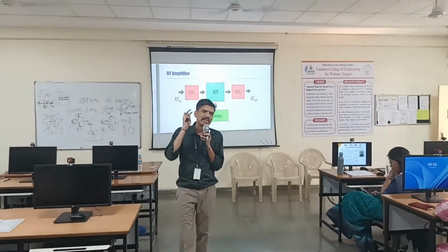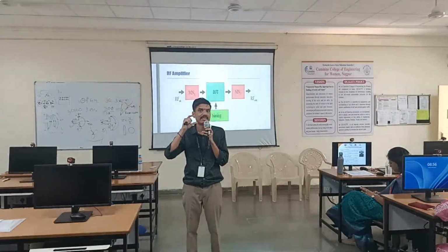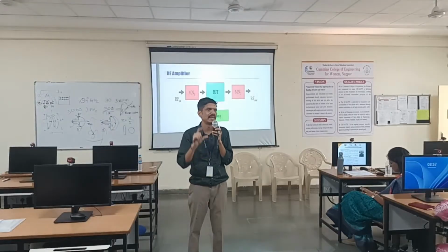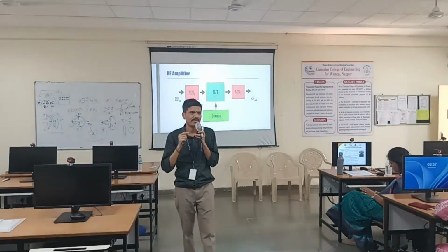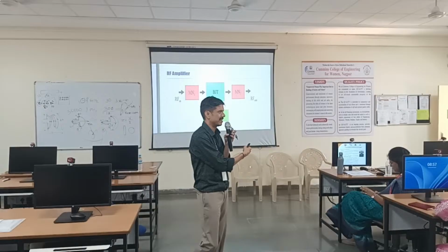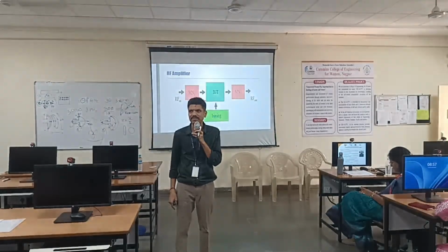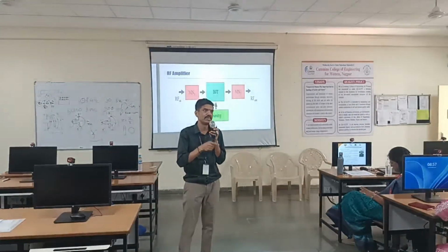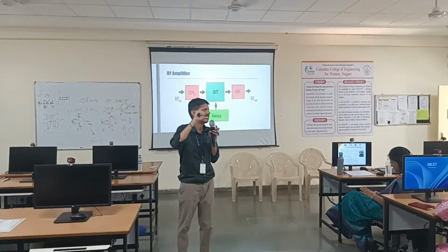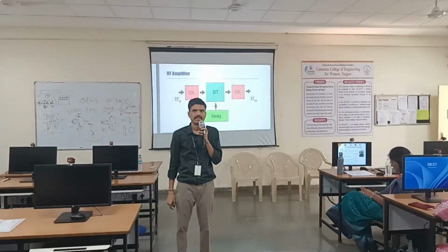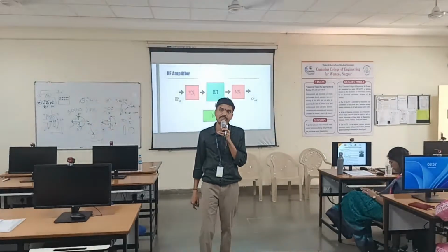See, there are 3 design parameters. To be honest, there are 4 design parameters for designing this transmission line. First is the dielectric substrate whose epsilon r we used to call the dielectric constant. If you are an antenna designer, your dielectric constant requirement is different, and if you are a PA designer, your requirement is different. They will fight with each other all the time, because in antennas we want intended radiation. So let us say you have a dielectric substrate whose height is 2 mm and another whose height is 10 mm. Can you answer which one is best for an antenna?